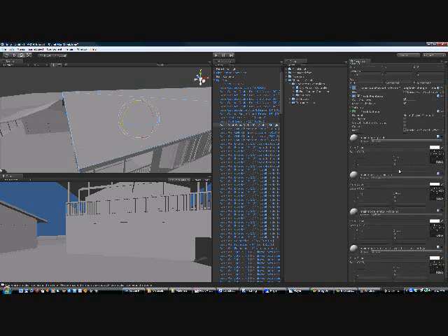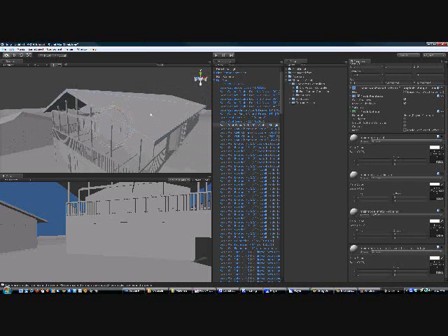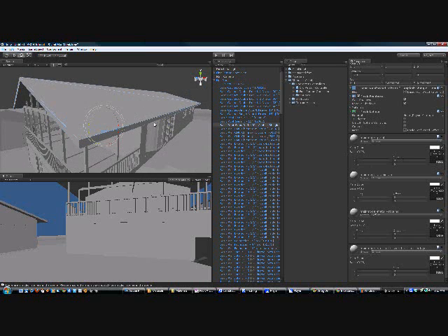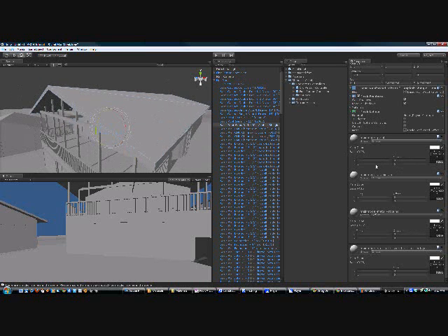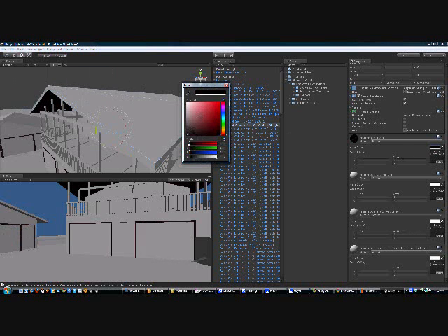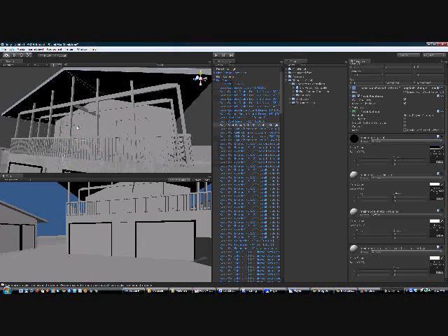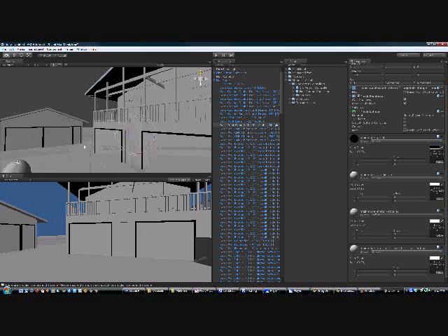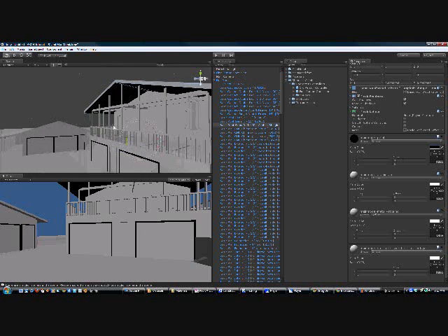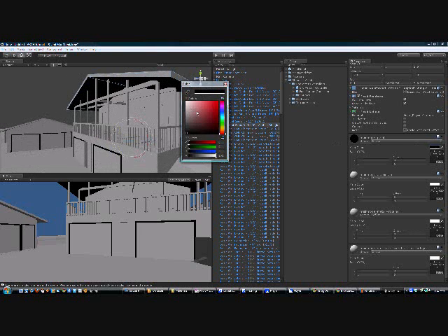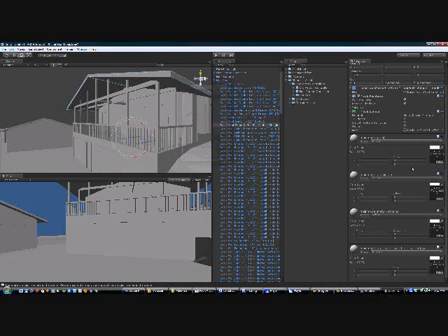You'll see on the right side there's a bunch of different materials that have been brought in from Revit, and the way, if it's not named intuitively, what you can do is just click on the color and turn it black, and now you can see what it's affecting. Obviously this is the door trim being affected. I just need a white door trim for now.